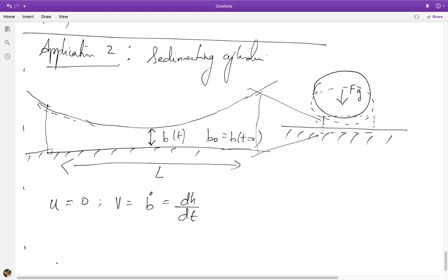What we now have to do, of course, is to specify what h is. Now let's say that our sphere has a radius of capital R, so R is going to be much larger than b. At the same time, the length L that we take, although it has to be larger than b, should be smaller than R, because we can't expect the lubrication layer to extend all the way to R, because if we go up to R, we are certainly inside the outer zone. So we have a separation of length scales where b is much less than L, which itself is much less than R.